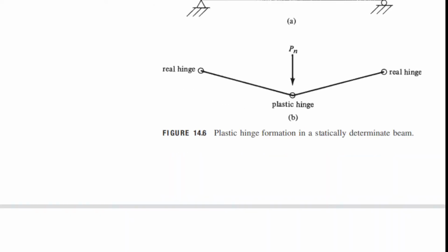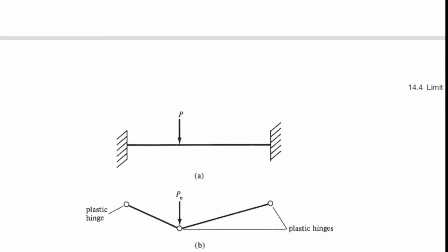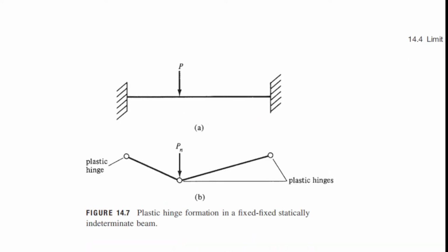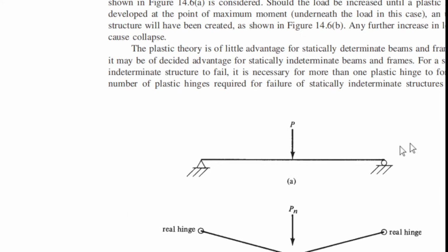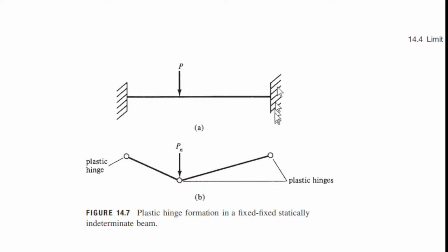Pin-like component. So, for example, instead of a simple beam, we have the fixed-ended beam. If we have the collapse mechanism on 1, 2, 3, on 3 points. Okay? So, we have the collapse mechanism on 2, in 1 point. 1 point collapse mechanism. So, if we have a fixed-ended beam, we have what? 3 collapse mechanisms before it totally fails.